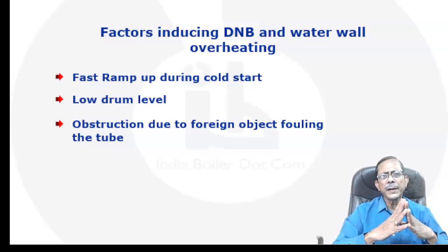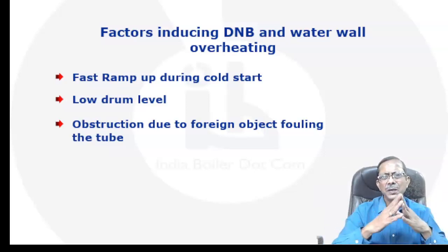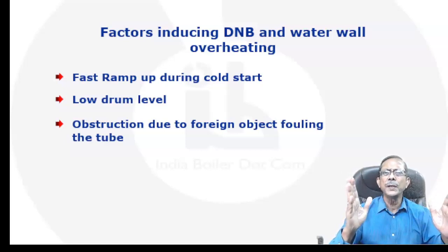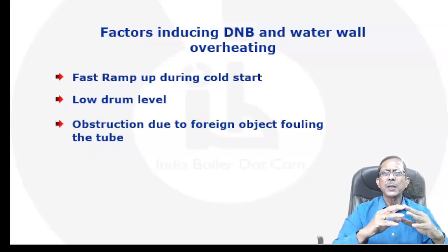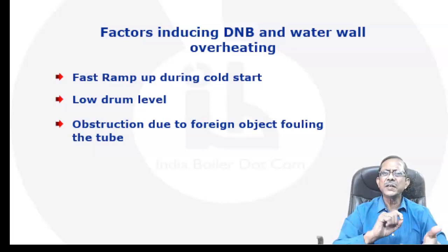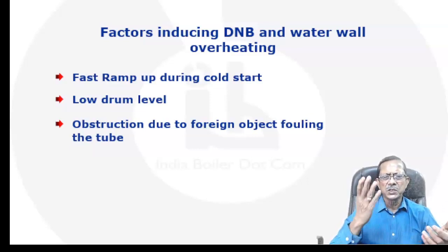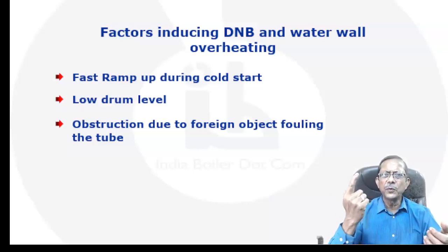One way of avoiding it is that whenever you have a steam drum manhole open, mostly during annual overhauling, make a strict regulation, a rule, that whoever enters the drum should have an inventory check. He takes 3-4 electrodes, he should come out with the tail of 4 electrodes, the remaining part. He takes a lot of cotton waste.